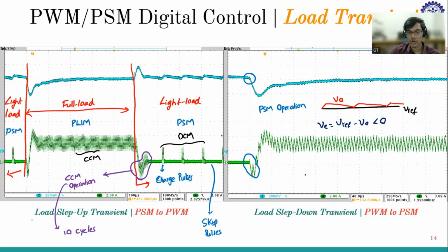Now if I move into the voltage mode control, Kp into V error will become not 0, but less than 0. And K derivative will be 0 because the previous error and present error is constant, and integrator we are resetting it to 0. So the overall control voltage will become negative, and because of which it is going in the other direction. This can be improved by adding some feed forward term here, so that it will go in the positive direction, and it will again improve this. Instead of going in the negative direction, it can directly go into the positive direction. Have you understood the reason why it is going in the negative direction?